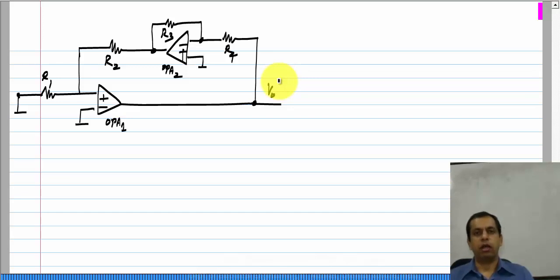Now, after a while, what happens is that if you design a negative feedback circuit with a number of op amps or any other stages, you will assign the signs so that negative feedback is valid once you learn this properly. Okay. But the most important thing here is to remember that all the nice properties of the op amp, such as virtually shorted inputs, are valid only if each of the op amps is in negative feedback, and you need to be able to make sure that this is indeed the case.